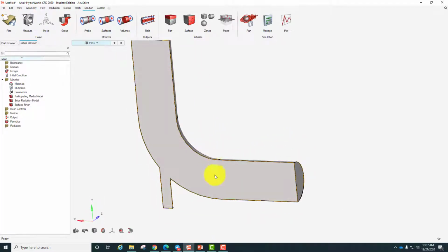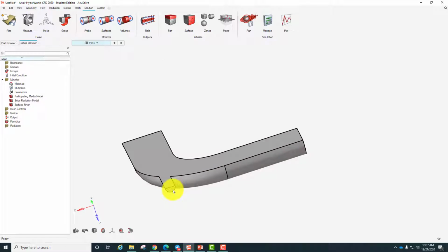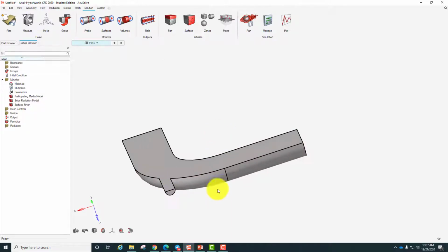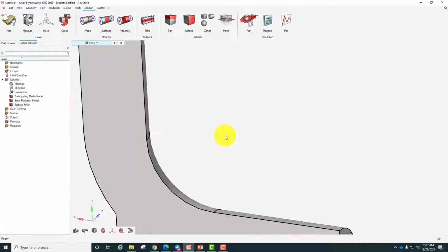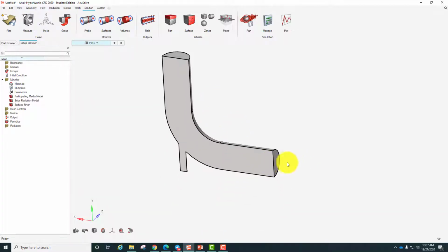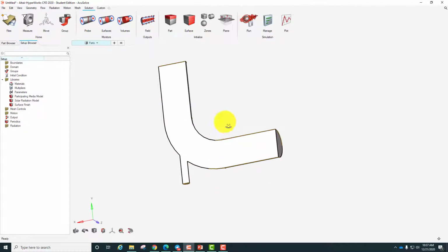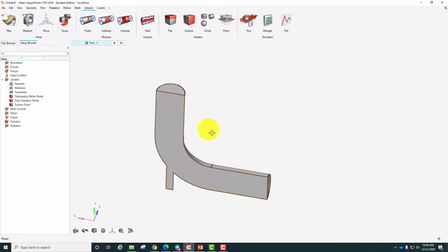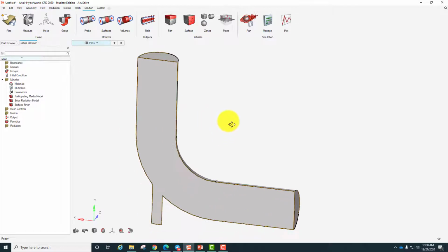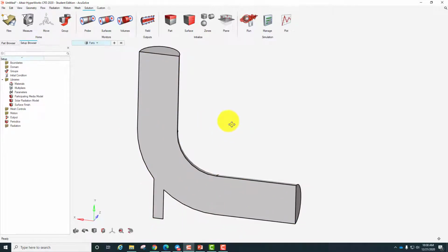So we want to evaluate the flow when this is an inlet of the part. Okay, this is the first inlet, this is the second inlet, the small inlet, and also the top one is an outlet. Okay, so the fluid will enter this mixing elbow from this first inlet and also the small inlet here, and then we'll go out to this outlet. Okay, so we will use the fluid as the flow analysis here.